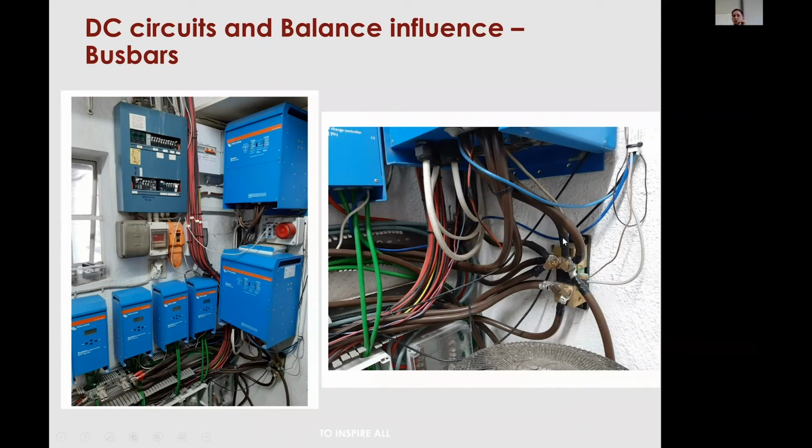So it all seemed logical that each one of those cables would be getting the same current and the same voltage. But in actual fact, especially if you have 3 lugs on 1 bolt, on the middle lug, you're starting to rely a little bit more on the fine edges and the screws to carry current as well as the flat plates. And the first lug is up against the copper bar of the shunt.